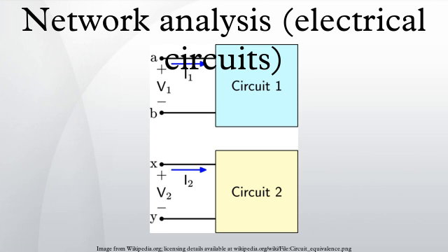For the three passive components found in electrical networks, the transfer functions are as follows. For a network to which only steady AC signals are applied, s is replaced with jω and the more familiar values from AC network theory result. Finally, for a network to which only steady DC is applied, s is replaced with 0 and DC network theory applies. Two-port network transfer function. Transfer functions, in general, in control theory are given the symbol H(s).